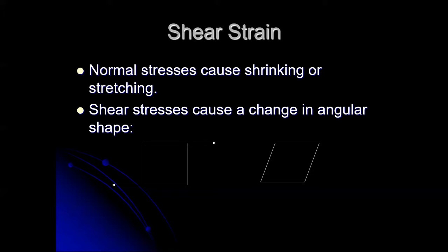This can be used in some cases, and in fact, in some cases, it is used to measure loads on things. We have what's called a strain gauge, and some variations of strain gauges work by measuring these angles, by changing their values as the angles change. Most of them work by using expansion or contraction. In a strain gauge, as it expands, its resistance becomes bigger, so we can electrically detect tensile stresses. And that's what's outfit on a lot of aircraft today. They put those in all sorts of critical places so the computer can measure how much stress the aircraft was under. So strain gauges work very well for that.